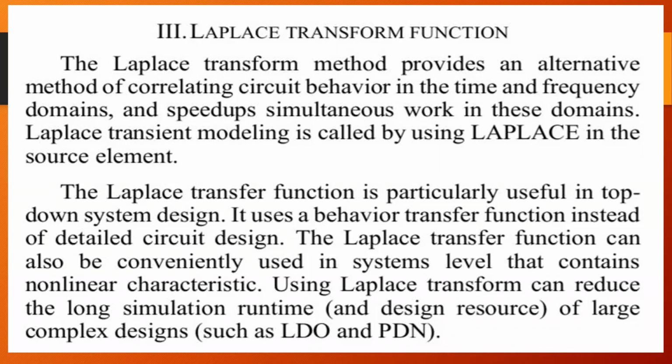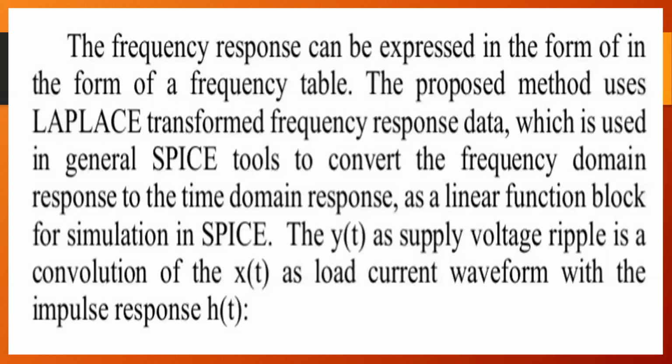It uses a behavior transfer function instead of detailed circuit design. The Laplace transfer function can also be conveniently used in system level designs that contain nonlinear characteristics. Using Laplace transform can reduce the long simulation runtime of large complex designs such as LDO and PDN.